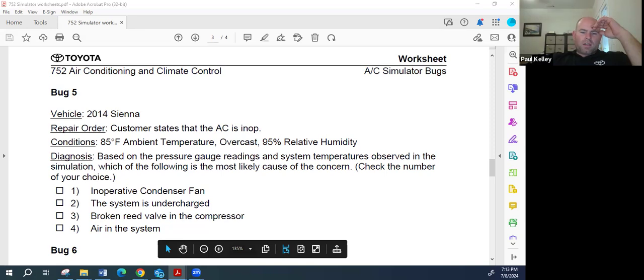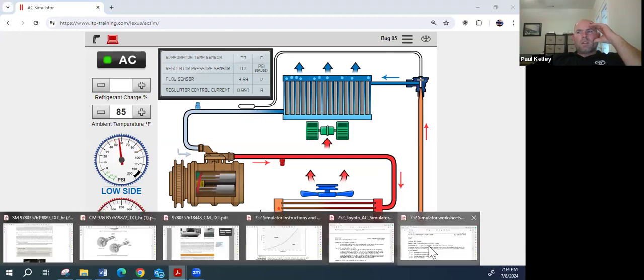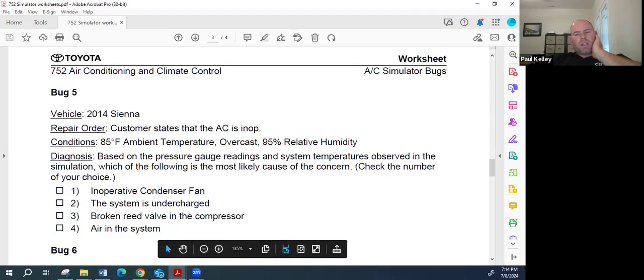So if you look at that again, the compressor's trying to pump, and the reed valve is letting it come back through into the low side. That's why your low side is spiking up to 90. Your 90 on the low side is horrible. Your 90 on the high side is horrible too. They're both horrible. And it's not because the compressor clutch is kicking on and off. It's just that the compressor's shot. The compressor's got a broken reed valve. Everybody agree with that? Anybody got any questions on that?